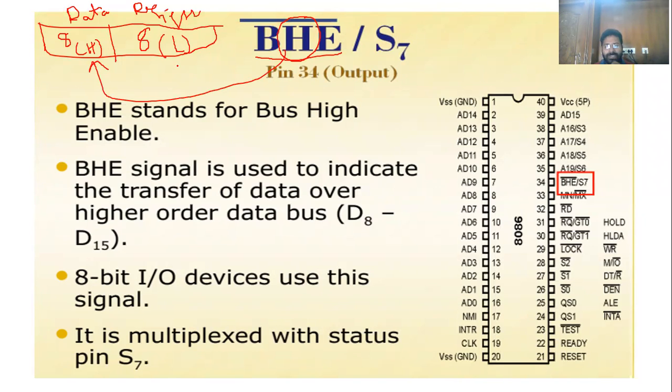You have 16-bit registers available for data purposes: AX, BX, CX, and DX. AX can also be written as AH or AL, and BX can be written as BH and BL. L stands for lower, H stands for higher.